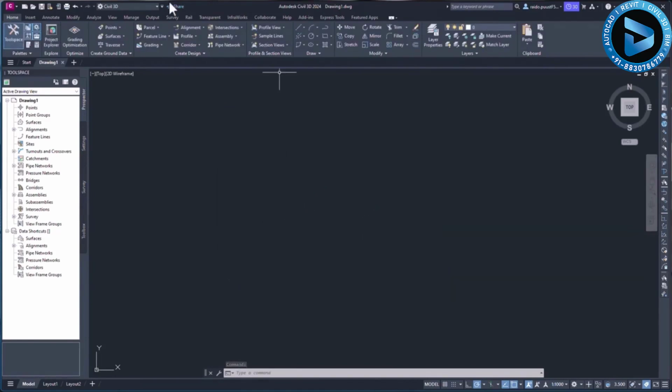If I want to use my Civil 3D as AutoCAD and I want to see simply the AutoCAD user interface, or let's say tools, then I can select from this top left corner 3D modeling or drafting and annotation. Drafting and annotation is basically the AutoCAD 2D user interface, and 3D modeling is the AutoCAD 3D user interface. You also have the AutoCAD Map 3D user interface by selecting planning and analysis. So Civil 3D includes AutoCAD, but also AutoCAD Map tools or toolset.